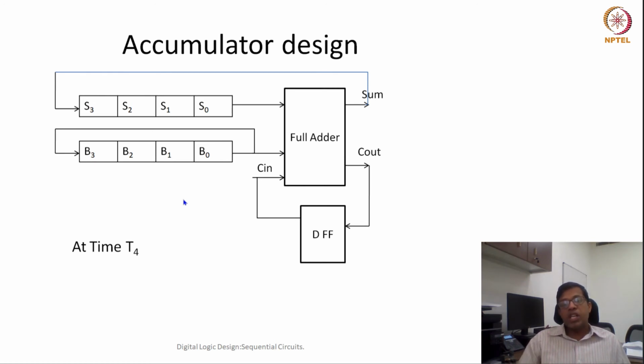So this way, using a single full adder, we would be able to design any n-bit adder in n number of cycles. The additional cost you see is this register. So 2 registers and 1 flip flop, and these registers would anyway be required whenever we are doing addition or multiplication or any other operation, because we would be doing everything within a clock period, and saving the operands in some registers. So that means this is essentially not an additional cost.